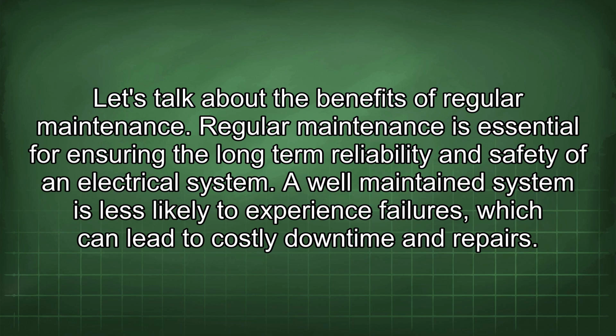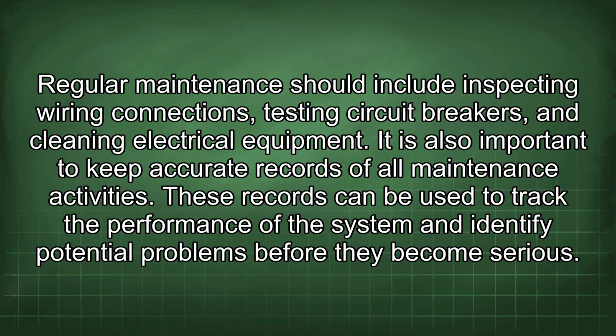Let's talk about the benefit of regular maintenance. Regular maintenance is essential for ensuring the long-term reliability and safety of an electrical system. A well-maintained system is less likely to experience failures, which can lead to costly downtime and repairs. Regular maintenance should include inspecting wiring connections, testing circuit breakers, and cleaning electrical equipment.